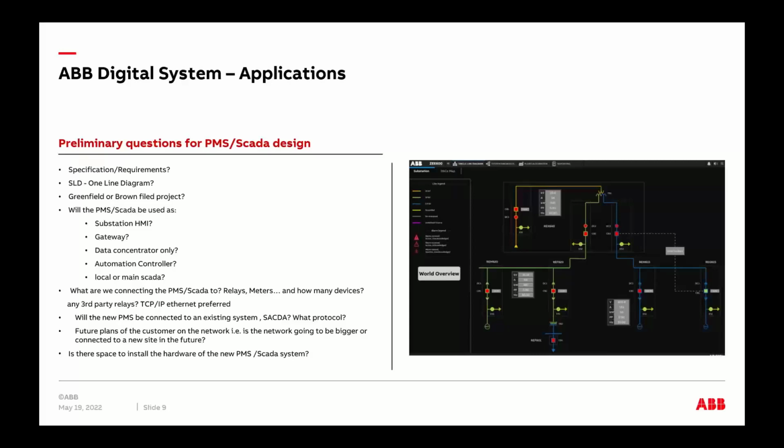When we're talking about the digitalization of a system, typically you want to stick with the TCP/IP type of Ethernet preferred. This is easy to engineer and easy to connect to. So any meter nowadays, when you say digital meter, it will have an RJ45 port, and you're pulling from that port directly. So that's at least one thing.